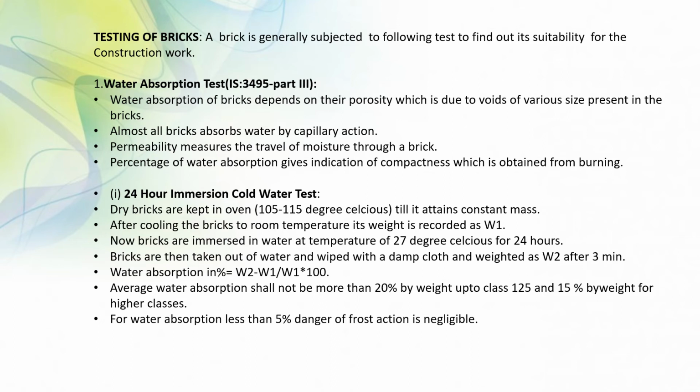And next, you can see this is an important parameter of bricks. Testing of brick. A brick is generally subjected to the following tests to find out suitability for construction work. Number 1, water absorption test. IS 3495 Part 2. Water absorption of brick depends on their porosity, which is due to voids of various sizes